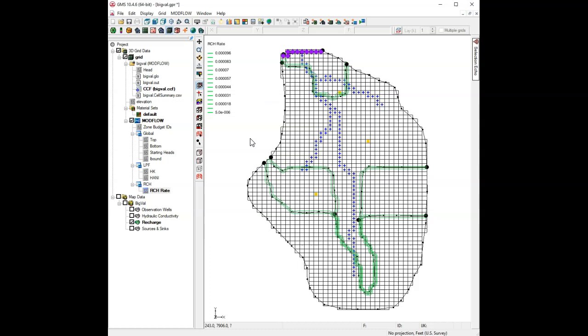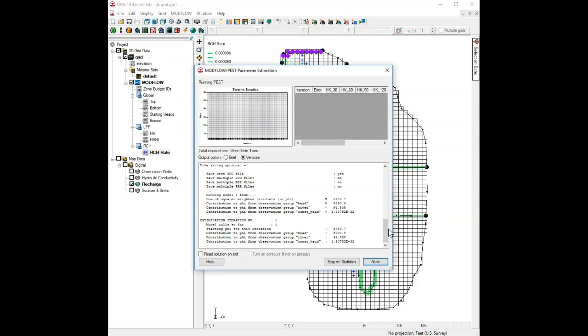And that just ensures that when it's launching all of these MODFLOW simulations that they all converge, and so by upping the number of iterations, we give it a better chance to converge on us. Okay, so now let's save this one last time, and now we should be able to run this model.